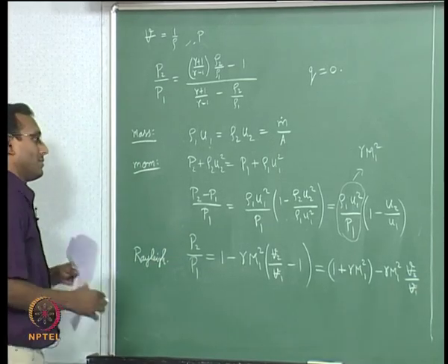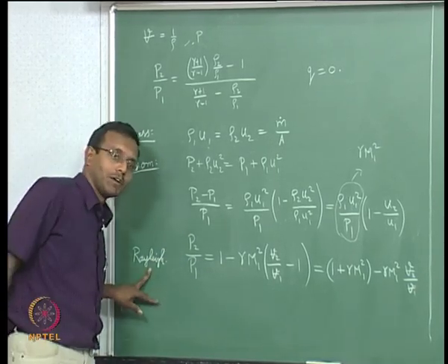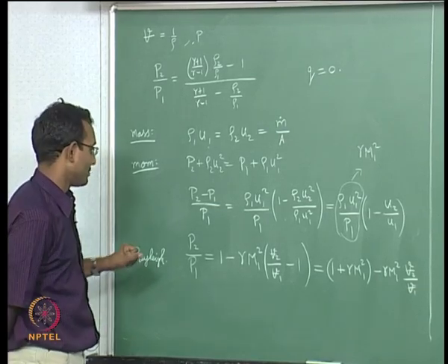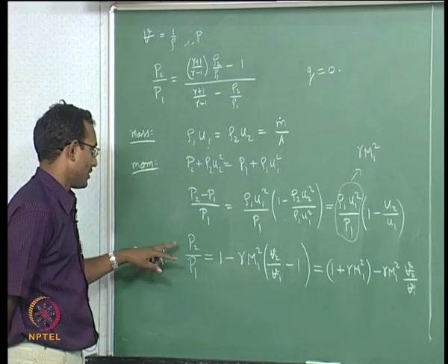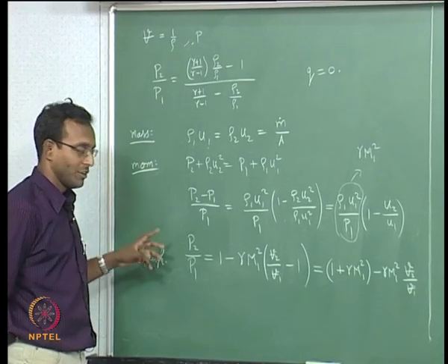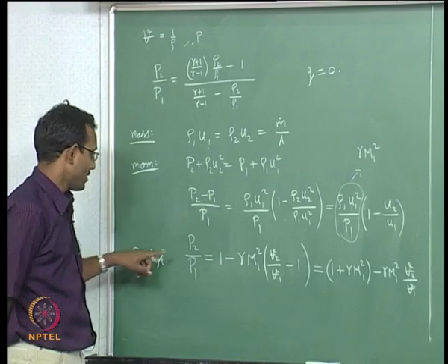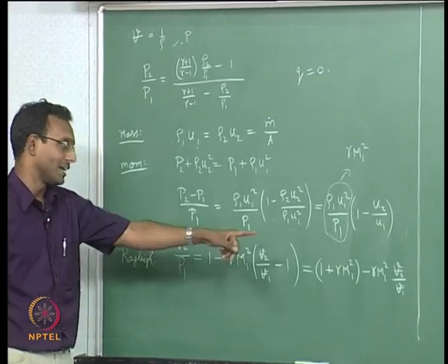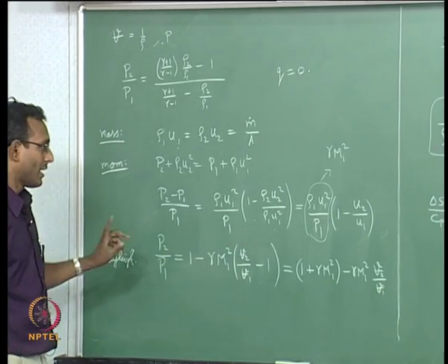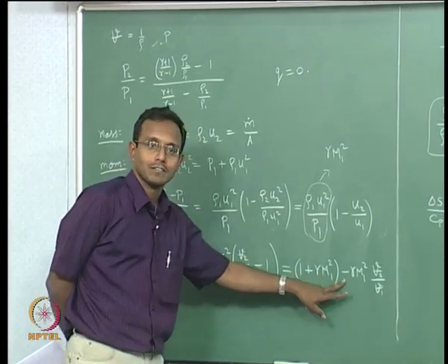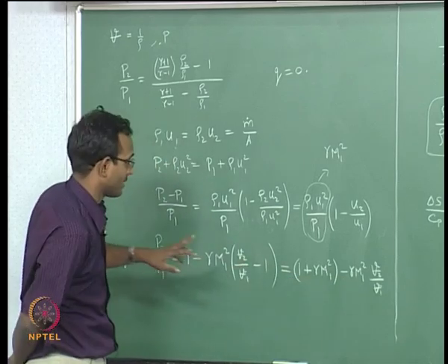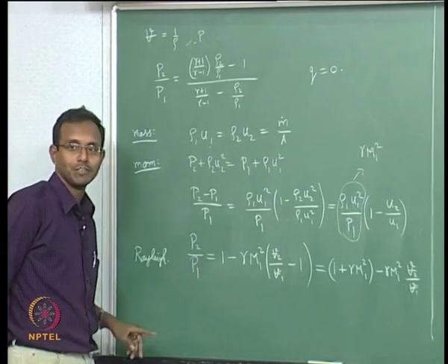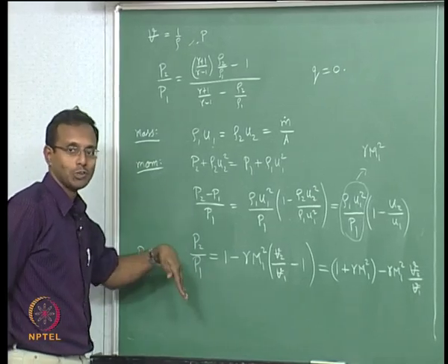Okay. This is conserving mass and momentum. That is all this particular expression is conserving. What I am seeing here is, for my flow we know mass and momentum are conserved, which means P2 and V2 are related this way, they are linearly related, P2 is proportional to minus V2. So I am going to have a negative slope.